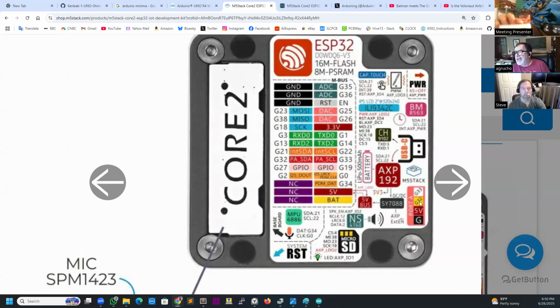Well, actually, you can program which one is TX and which one is RX. In the ESP32, you can do whatever you want to match the connector. The connector is red, but it can be anything. You can use I2C here or whatever. On the original, it's red too.